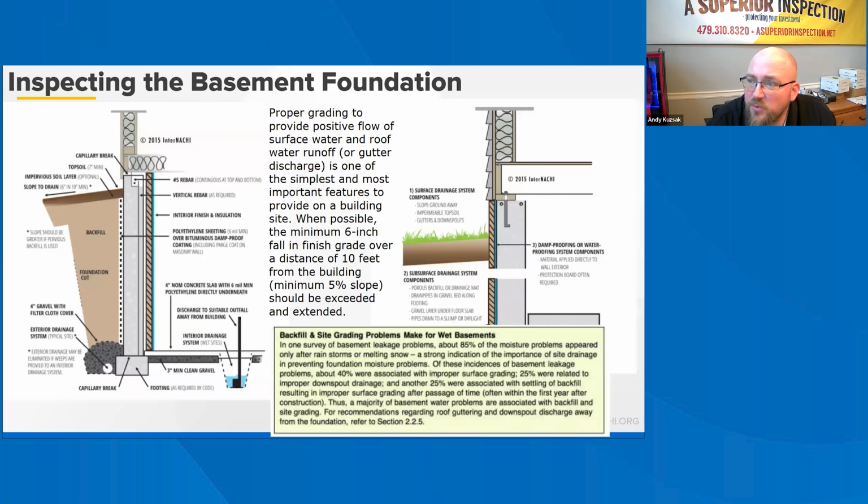The degree of protection required for any given site and selected foundation type is determined by the inspector to ensure it meets or exceeds minimum building code requirements. The building standards and recommendations in this section aim to teach enhanced moisture resistant techniques. Foundations that create below ground spaces on wet sites require special attention. During an inspection, attempts to remedy moisture problems through waterproofing may be observed, although such efforts could have a shorter lifespan than the building.